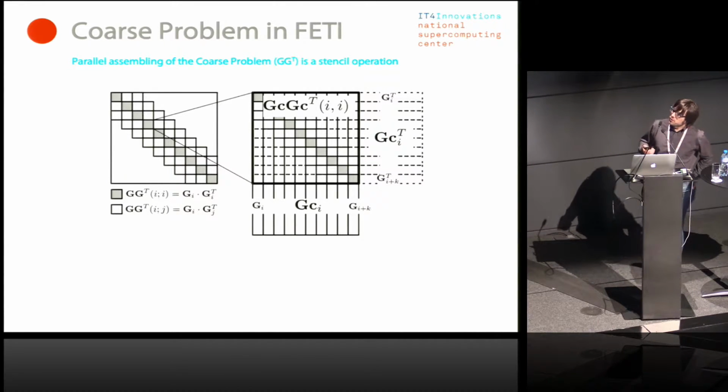So the factorization is usually in this step the longer, but we are still talking in a few seconds to get the factorization. And then actually, if we would calculate the inverse of the matrix on a single node, that would be the most time-consuming part, because we have to solve a very large number of right-hand sides. But then, since each MPI process in hybrid FETI solves for only 6 right-hand sides, the solve is extremely fast.